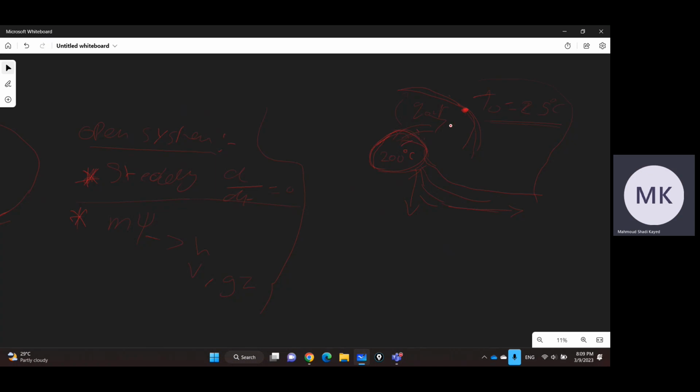Instead, the exergy transfer by heat in this case is converted to exergy destroyed. Because when we take the boundaries around the system and make an exergy balance, the exergy transfer by heat is (1 minus T naught over the temperature of the boundary) multiplied by the Q leaving that boundary.